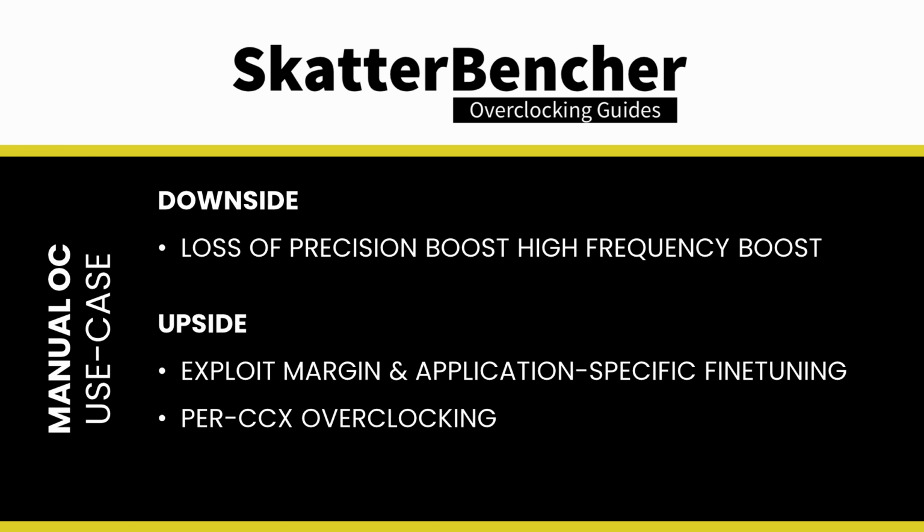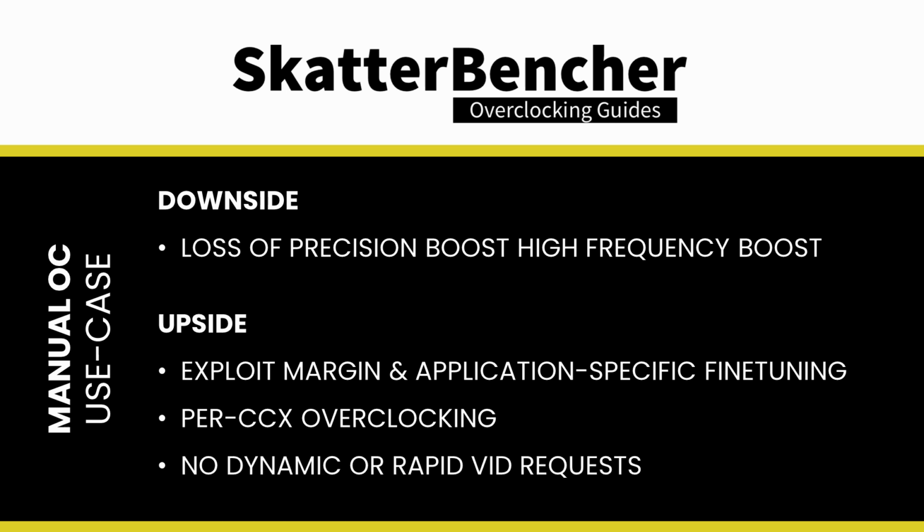So we can exploit the fact that some CCXs may overclock better than others. This is particularly relevant for the Ryzen 9 7950X and 7900X. Thirdly, by setting a fixed voltage, we avoid the CPU dynamically and rapidly updating its VID requests to the VRM controller. This alleviates stress on the VRM and typically yields lower temperatures.